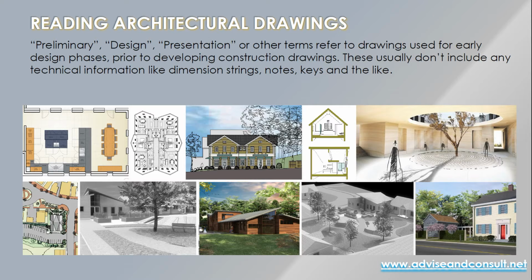We hate it when clients make changes during the construction drawings, because you'll see they're very complicated and they have an extensive number of internal references back and forth. Clients frequently don't understand that in a construction set of drawings, if you ask for a change, it doesn't change just one drawing. It changes probably 6 or 10 drawings, and you have to chase through all of those changes in order to be thorough about making the change.